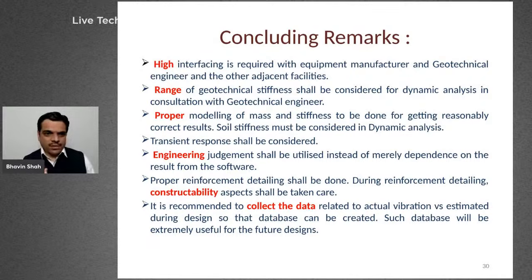Second point, the range of geotechnical stiffness shall be considered for dynamic analysis in consultation with the geotechnical engineer. Then proper modeling of mass and stiffness is to be done for getting reasonably correct results. Soil stiffness must be considered in dynamic analysis, according to me. Transient response shall be considered, as we just discussed in the previous slide. And over and above this, engineering judgment shall be utilized instead of merely depending on the results from the software.